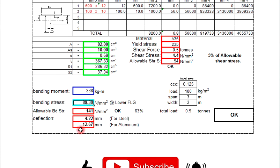Just now it was around 100, so 110. So this one is 110. So you make the bar plate thicker, and then you will reduce the bending stress. Even the size also. Let's say you want to reduce from size 110, so you use a bigger size, let's say 150, and then it becomes 52. See here, 52, right? Because in this calculation, the bigger the profile that we are using, the stronger.